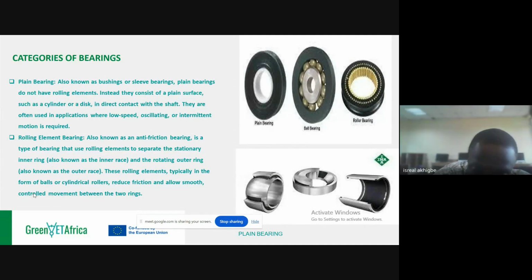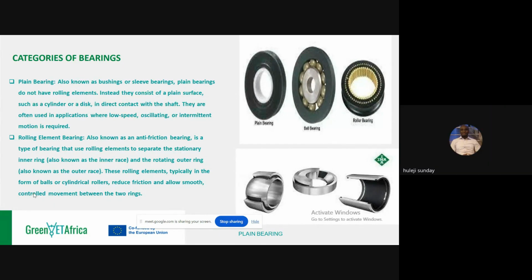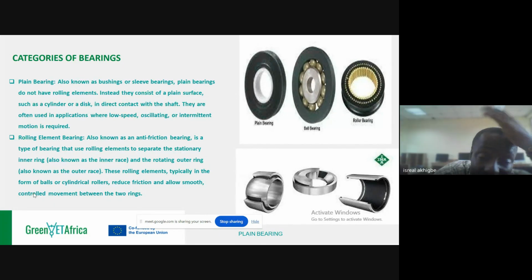Then if your driver is a smaller diameter and your driven is a large diameter, it will run at a lower speed but a higher torque, because of the difference in circumference. So that's basically pulley ratio, just the diameter differences. So what's your second question?